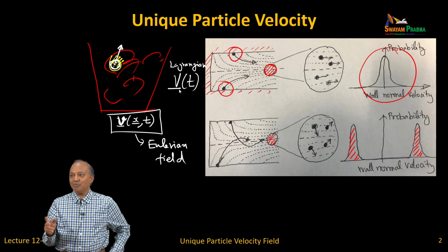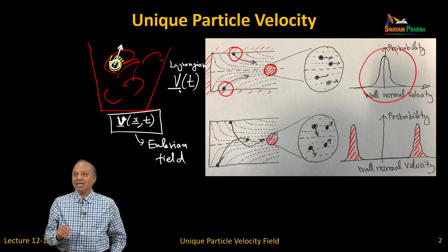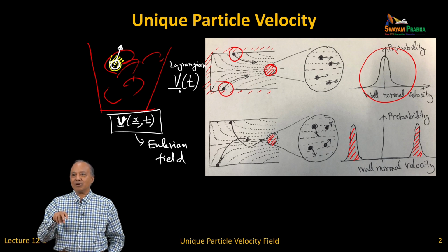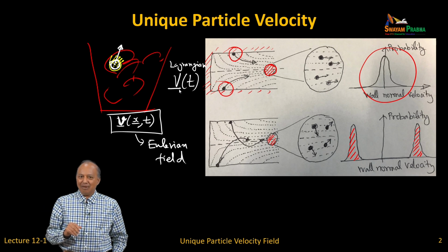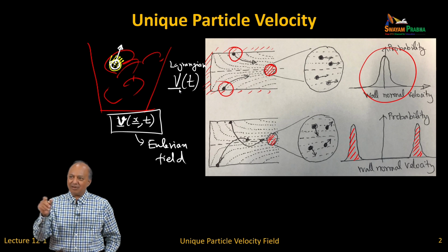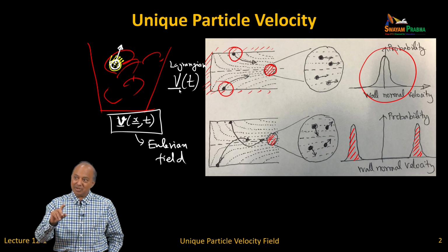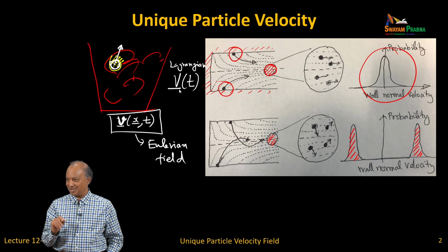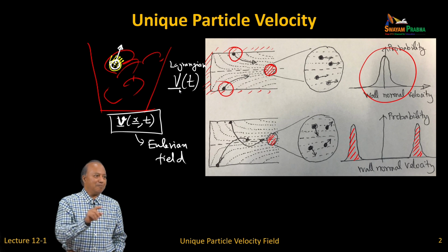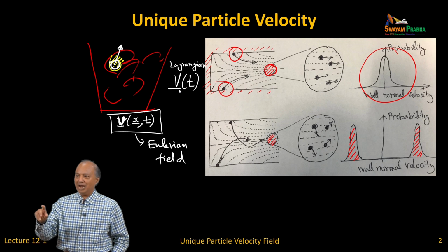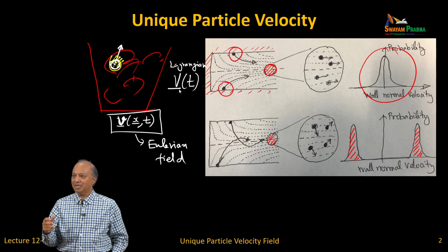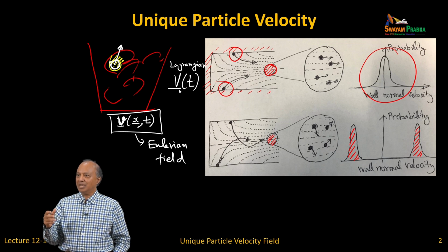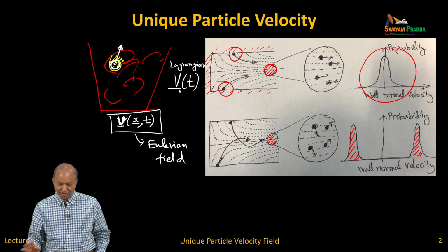And so, what I am trying to say is that the subgrid velocity for gas depends on turbulent eddies. Okay. But subgrid particle velocity depends on the inertia of the particles. That is why people solve granular, because the particle velocity can be substantially different from the average. Okay. And that is something for you to remember.